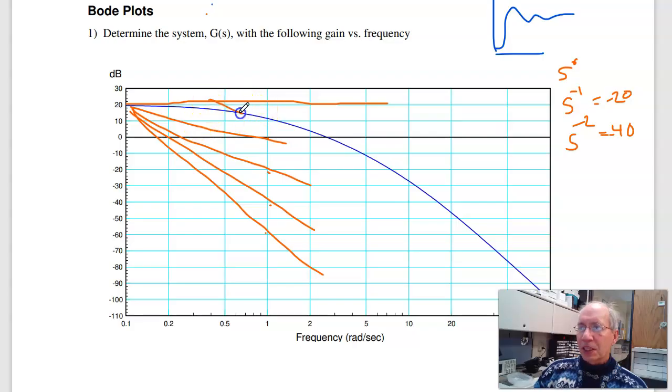So like to take this guy, oops, I didn't draw that quite right. You've got to get the slope right. So there's my slope. That'd go right about here. Take this slope, comes in about like this. The next slope. Where they intersect are your poles.